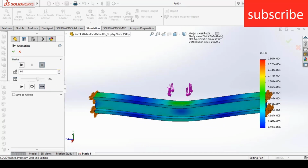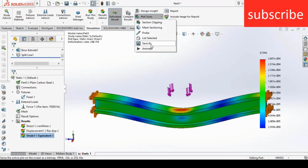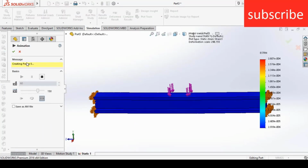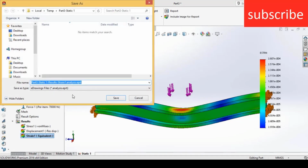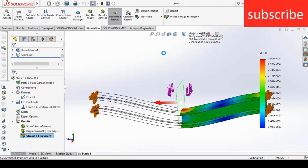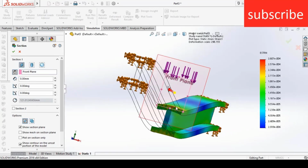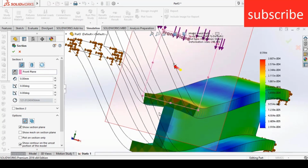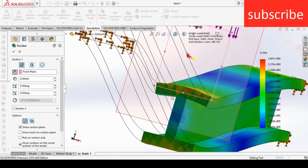Click on stop. Now click exit. Now click on plot tools, and you can save as this or animate it. Plot tools, click save as. You can save the analysis in eDrawings files as per your requirement if you want. Okay. And section clipping. Section clipping is the same thing as I told you. If you want to see where the strength is at any point, length, width, or anywhere else, you can easily see from here.